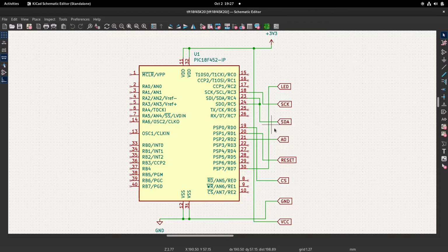But our display has a single pin for the data, but it's bi-directional, so you can read and you can write data to it. We will mostly be writing data to it, but you can also read the device ID and you can read the memory, which I did. It was a bit of an adventure, and let me know if you really have to read the memory of these screens, because you need to turn off the hardware SPI and send a dummy clock and then keep reading, so it's a bit tricky. I'm happy to tell how it's done if you want to know about it. But basically the input and output pins will both be connected to the data pin, so that's fine.